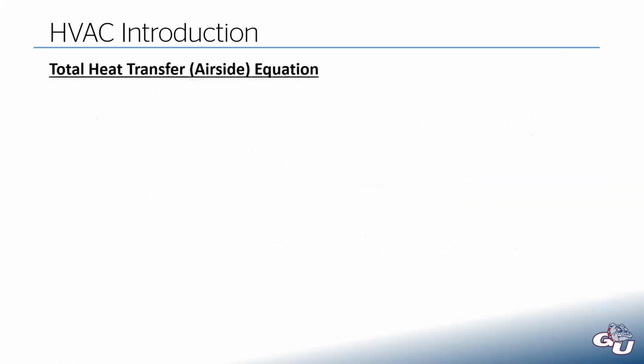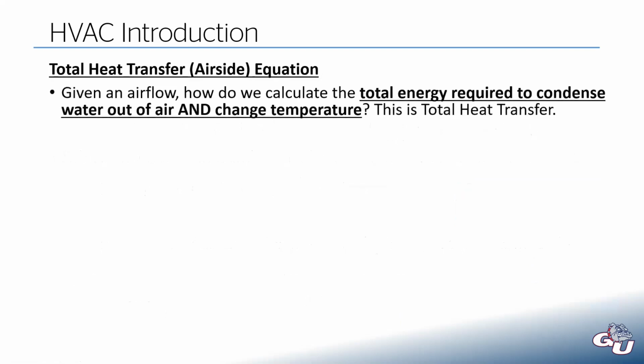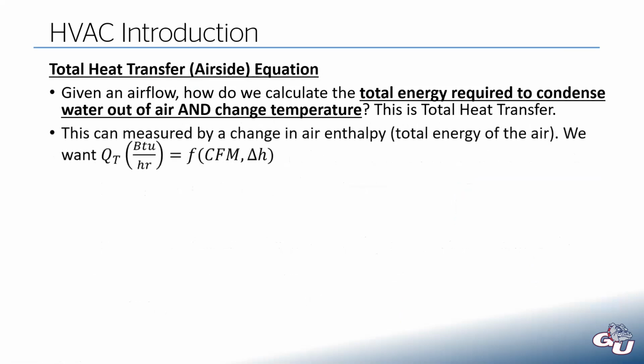The third equation is the total heat transfer. So if we know our airflow, how do we calculate the total energy to condense the water out of the air and change the temperature? So this would be both. This is expressed as a change in air enthalpy.